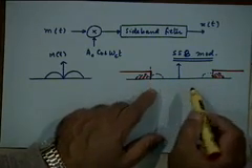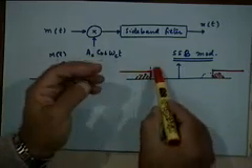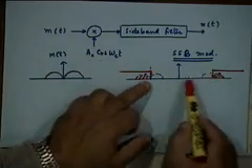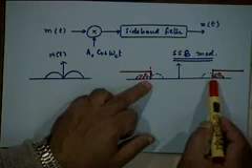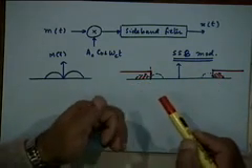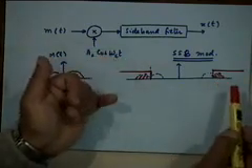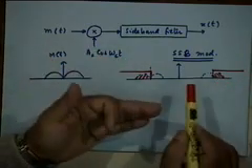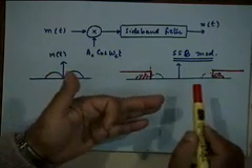If you want the lower sideband, you should have a low pass filter with a cutoff frequency of fc, right? So depending on whether you want the lower or the upper sideband, you can use an appropriate filter, which ideally could be either high pass or low pass.